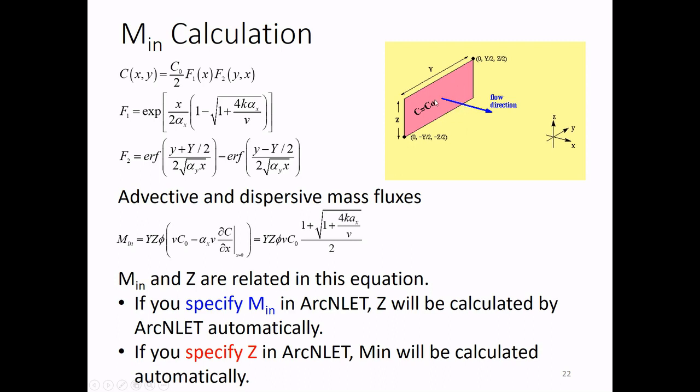Concentration here is higher, concentration here is lower, so it just disperses out. So this is how we do the calculation. This part is advection, this part is dispersion, right? And you see here, V we already took care of in the flow model, and alpha is the dispersivity parameter along the longitudinal direction, and here is a derivative with respect to x. So we have an analytical solution.